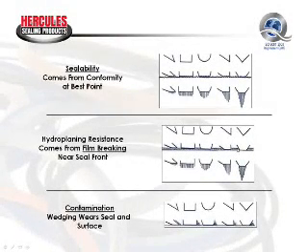two seals. On a double-acting piston application, on the side of the piston where there is no pressure or low pressure, the seal must allow enough trapped pressure to bypass the seal lip so that it doesn't build up between the two seals. However, if the low-pressure seal lip is sealing too effectively, you trap pressure between the two seals, and if you trap enough pressure, you can actually cause the seal to extrude on the piston, trapping seal material between the OD of the piston and the bore of the cylinder.